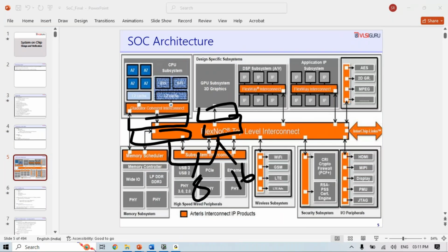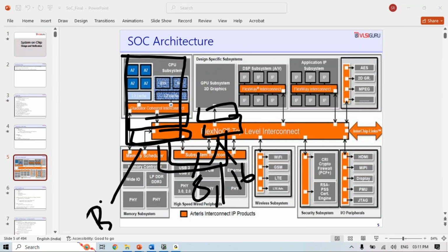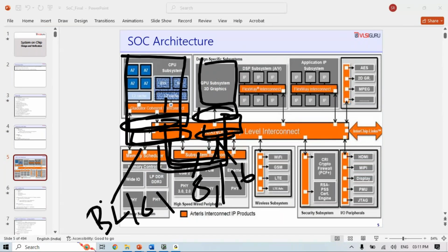Advanced packaging is another type, which supports either 32 lanes or 64 lanes. So as in other protocols, the negotiation happens at the die-to-die adapter layer and the physical layer, where they agree upon the link width, which protocol they are going to work with, and the various packet formats. Once that is done, the packet transmission happens.